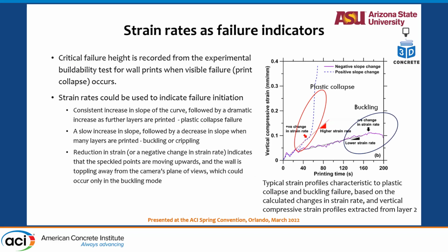Simply what we've done is look at the vertical compressive strain as a function of time. The vertical compressive strain changes. You see here there's a significant increase in vertical compressive strain with printing time. We use that location, or that time, or the number of layers printed at that time, as an indicator of initiation of failure.